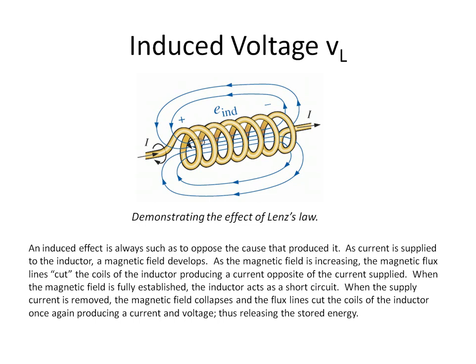As it's increasing, it's growing, and that causes the coil to cut lines of flux. And so when it's charging up, it's actually acting as a generator. But the interesting thing is that the energy that it's creating, especially the current, is opposing the current that's charging it up to begin with.